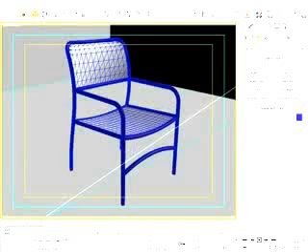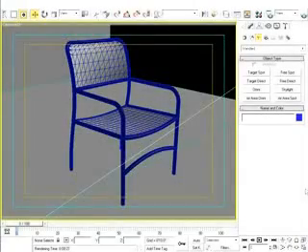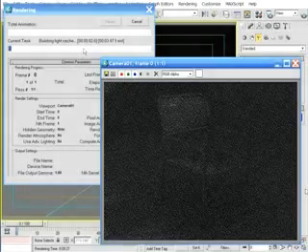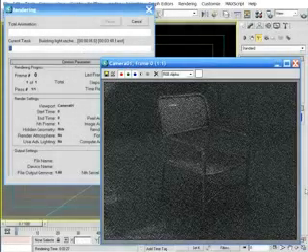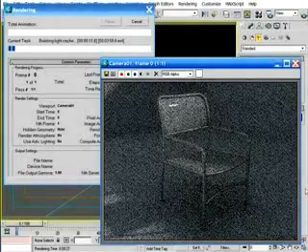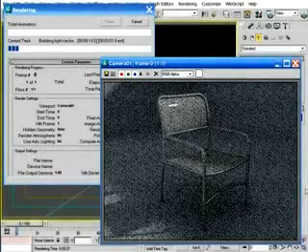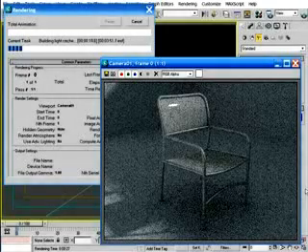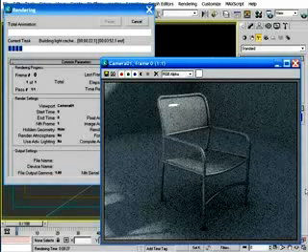Now, with that said, the first feature that I want to talk about is progressive path tracing. There are so many great things about this program, VRay, and I think one of them would have to be the wide range of tools available to get the same end result. In this case, progressive path tracing is certainly another tool that should not disappoint. It's a rendering method that uses the light cache algorithm to progressively render the final image all in one step, bypassing all of the normal steps that are processed individually one at a time. Steps like primary bounce, secondary bounce, image sampling, depth of field, caustics, and so on. So instead of creating these steps individually, it processes everything all in one larger step.